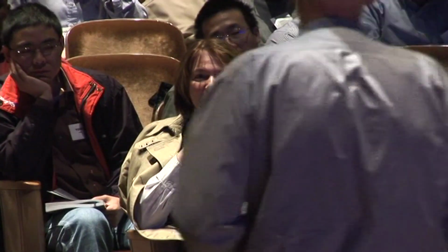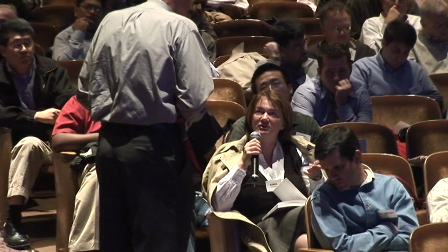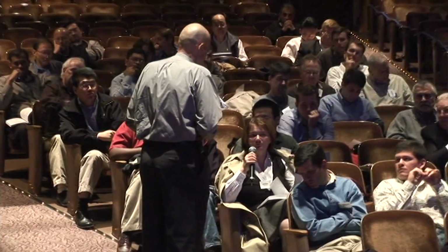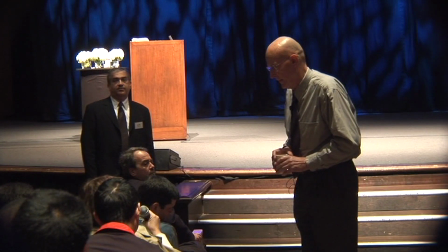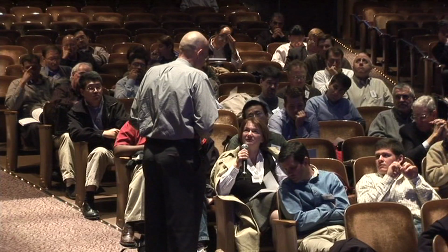There you go. You emphasize that it's very important to properly treat p-delta effects. I'm just wondering, do you have to do something special to really model them properly in the analysis? From my experience, often you would have frames, say moment-resisting frames that are coupled with some gravity columns, and it's really the moment-resisting frames that are taking care of this overall sway effect that causes additional p-delta effects. But often what I find in programs is that the tributary loads, the gravity loads that are affecting these effects, are not adequately treated. So I was just wondering, how do you go about it in Perform?